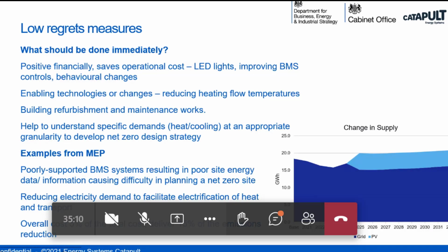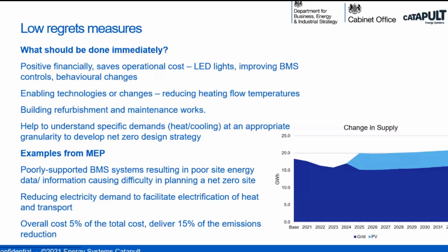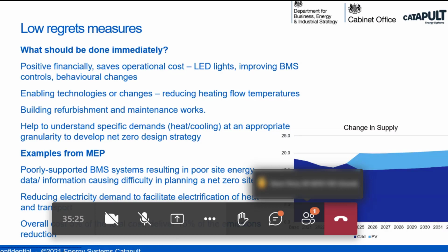Turning to the MEP experiences, we found a number of building management systems in very poor condition. They were either underinvested or ignored, or people were just using them for manual control. We suggested, and have actually enabled, getting some of these building management systems back into good condition, which is relatively low cost and gives the benefit of good data to help direct intervention effort in order to reduce energy consumption.